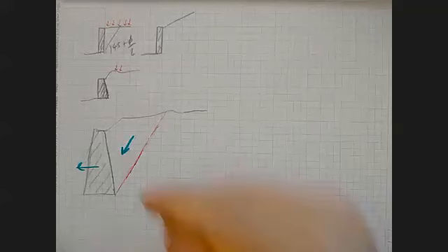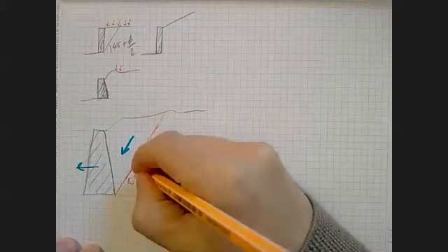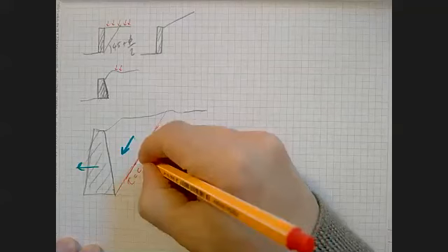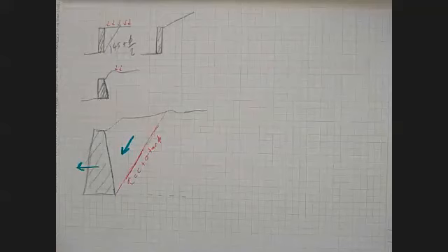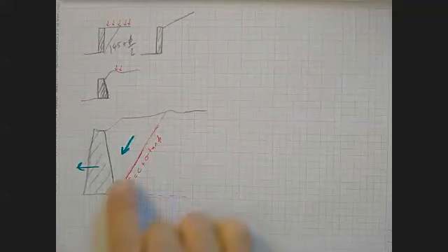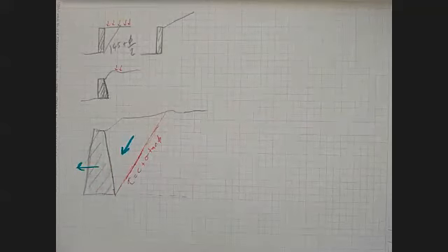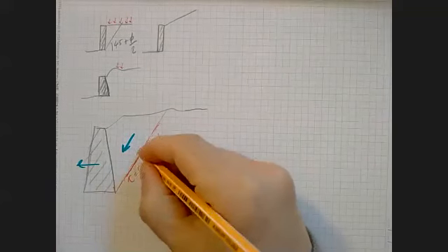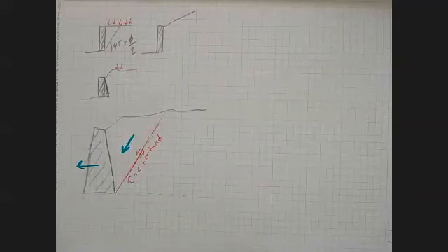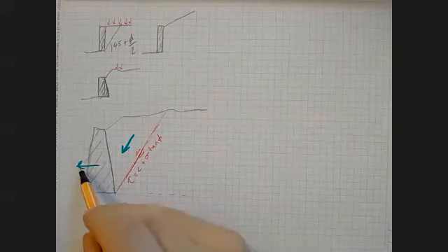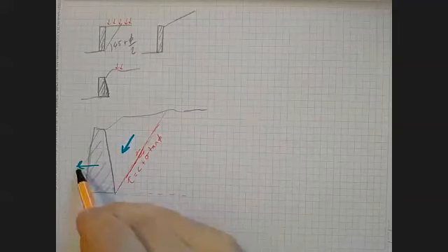So here your shear strength is known to Coulomb. Coulomb knew the shear strength on the plane and knew that there has to be a failure there. Of course, you also have to have another shear plane, because the wall is moving horizontally, but the wedge is moving down.